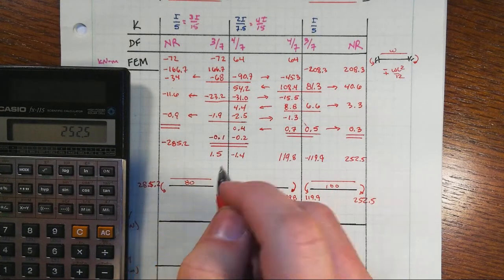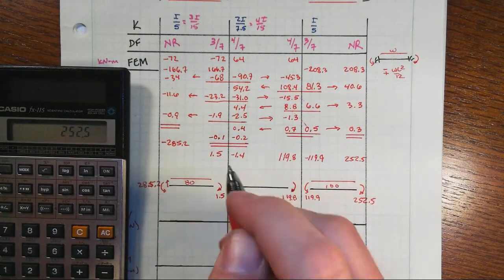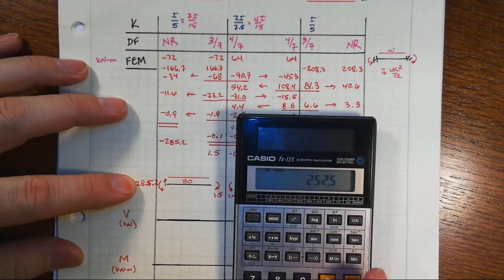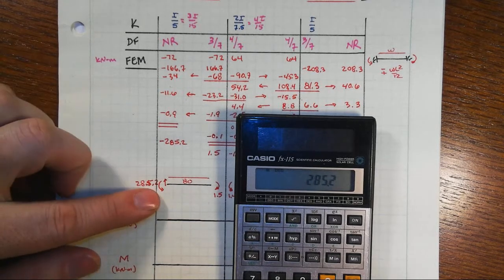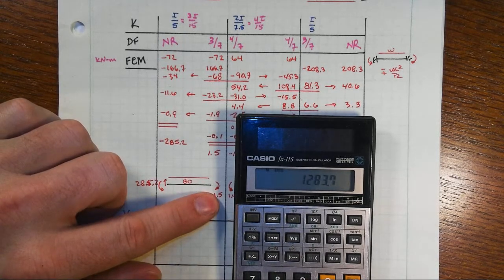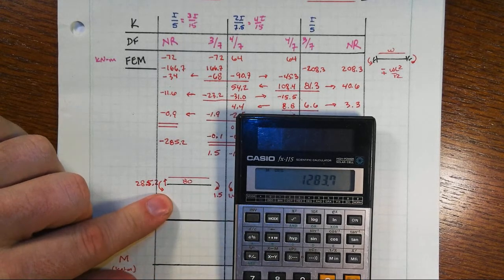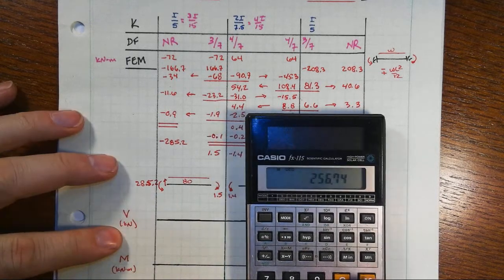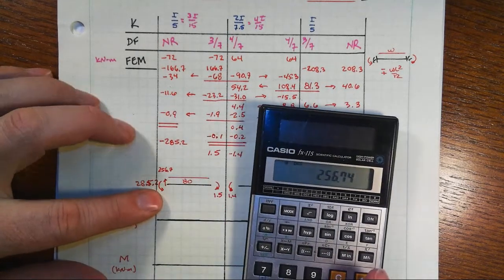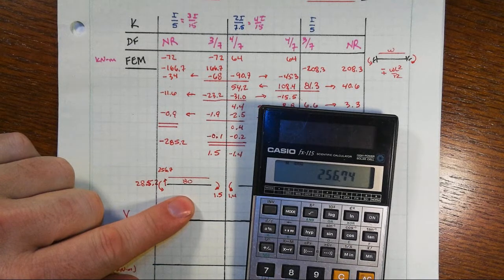Our left hand shear is going to be acting upwards, I think, so we've got 285.2 going in a counterclockwise fashion, plus 80 times 5 for the load times 2.5 for its moment arm, and minus the 1.5 that is out here at the far right. Then we divide by the length of the member for the moment arm for that shear, and that'll be 256.7 kilonewtons for that shear. We could subtract off 80 times 5, or 400, and we get 143.3,